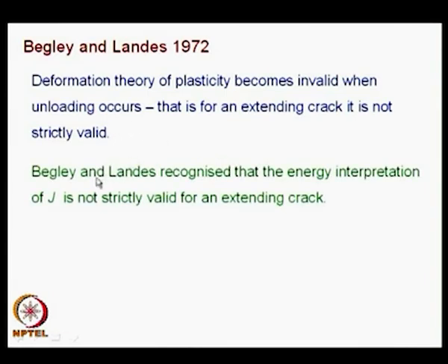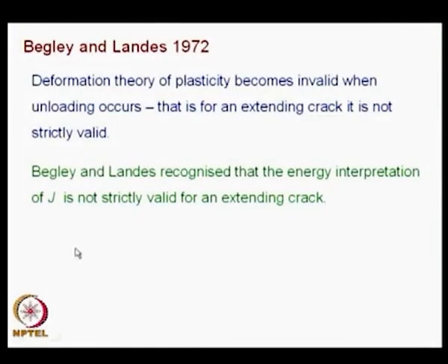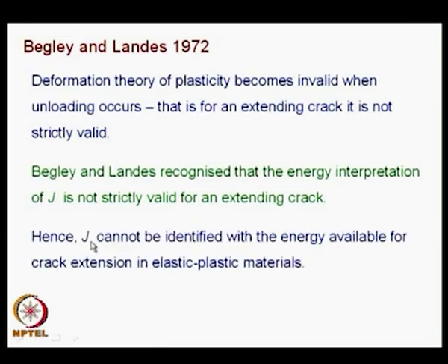In view of that, Begley and Landers recognize that the energy interpretation of J is not strictly valid for an extending crack. In the case of nonlinear elastic solid, this definition is all right, but once you take it to elastoplastic analysis, the interpretation that J is the energy release rate is not strictly valid for an extending crack. Hence, J cannot be identified with the energy available for crack extension in elastic plastic materials.